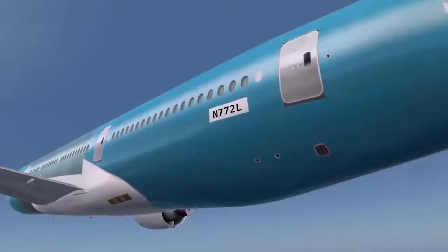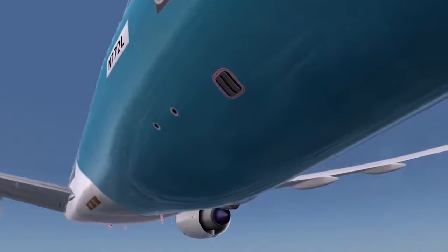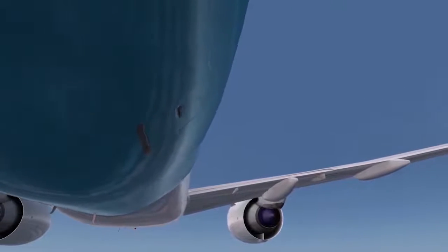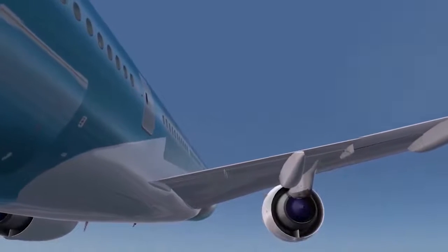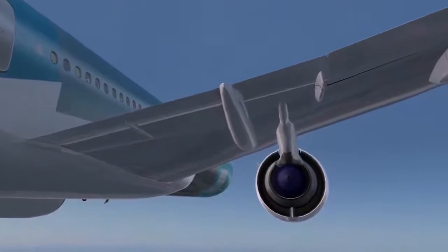Trim air from the left engine bleed system works with the flight deck, 3 passenger cabin zones, and the aft cargo compartment. Trim air from the right engine bleed instead is added to the 3 other passenger cabin zones, forward cargo compartment, and the electronic equipment compartments.